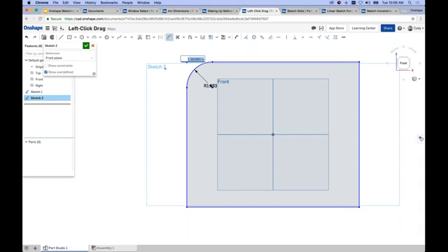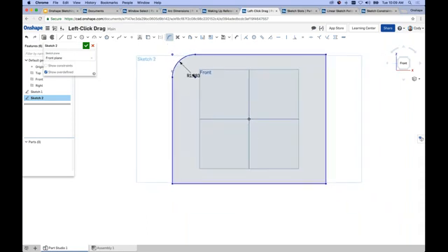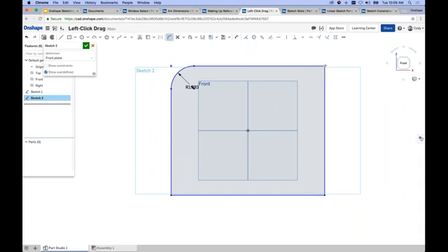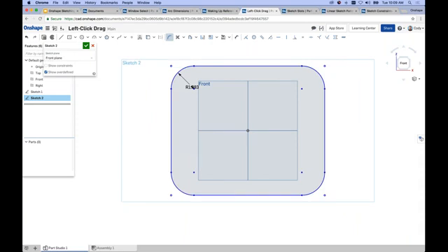One other tip that I would give you, this is just kind of a random tip, but if you've created your first sketch fillet and then you continue clicking points, it will continue placing radiuses of the same size on those points. So you should really only have to define the radius once and then go through and select each point where that radius should apply, and it will apply the radius and give it the equal constraint, meaning this dimension will drive the sketch fillets that were created during that time, right?